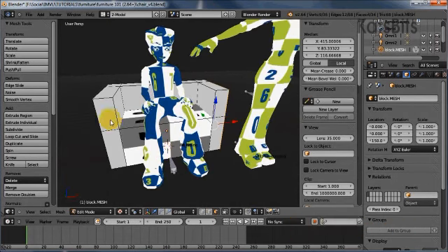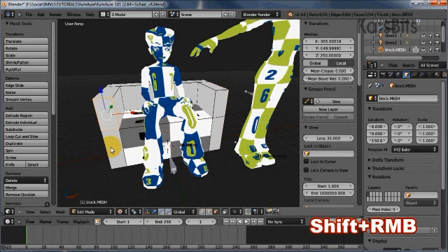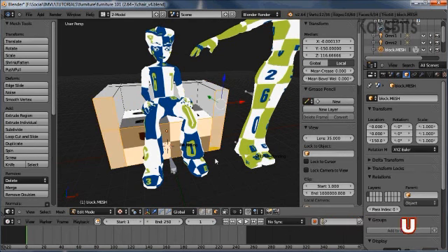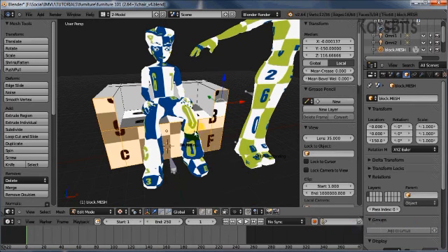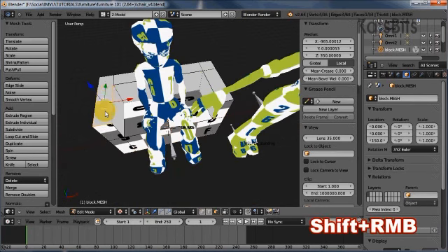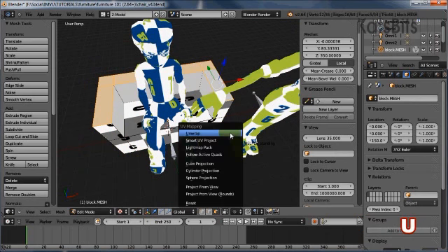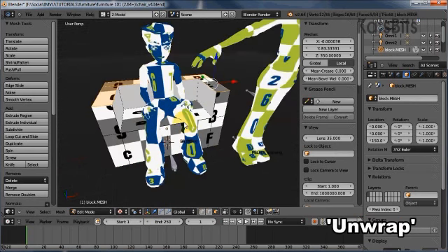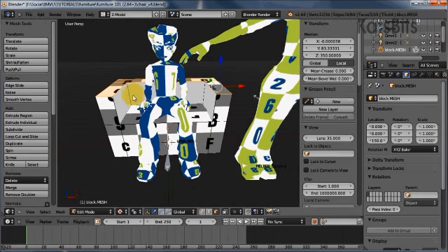And for the front, we can right mouse Shift and then U again. For the top, right mouse shift, and again. Now for the inside we can either do it as one selection, or we can do each side individually depending on what we are wanting to do.